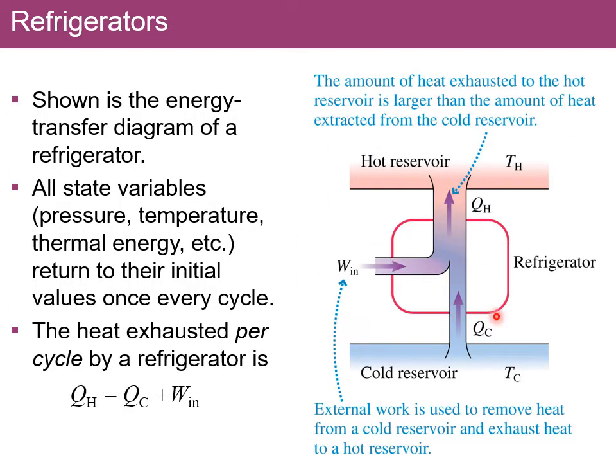Here we have an energy transfer diagram of a refrigerator on this slide. Here we see energy is drawn from the low temperature reservoir, work is done on the system, and then an amount of energy equivalent to the energy drawn from the low temperature reservoir plus the work done on the system is expelled into the high temperature reservoir. At the end of each cycle, all state variables are returned to their initial states.